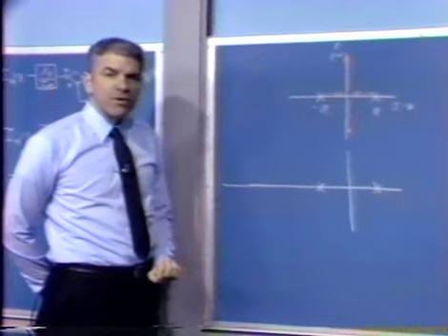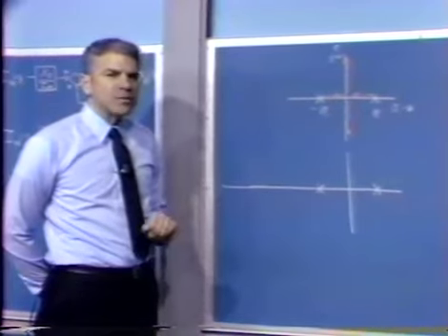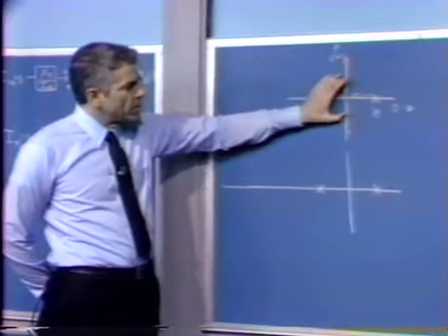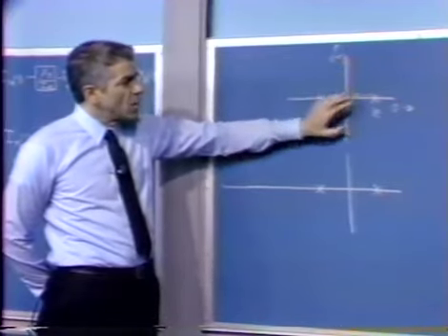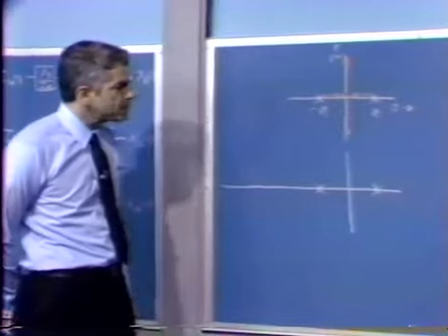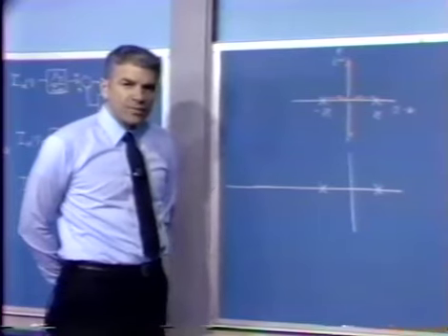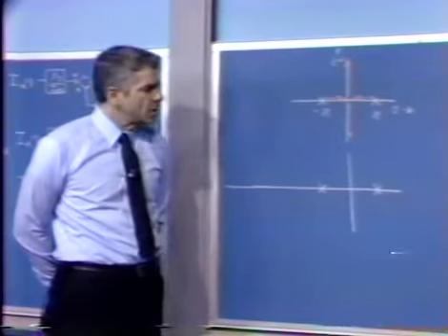Of course, there are additional low-pass elements in the system, and so we wouldn't be able to even get to the pair of poles on the imaginary axis without having some dynamics associated with the amplifier. The thing to do is add a zero. That oftentimes works to help stabilize systems.